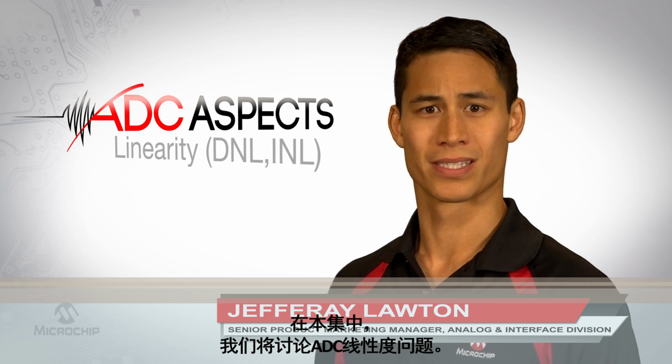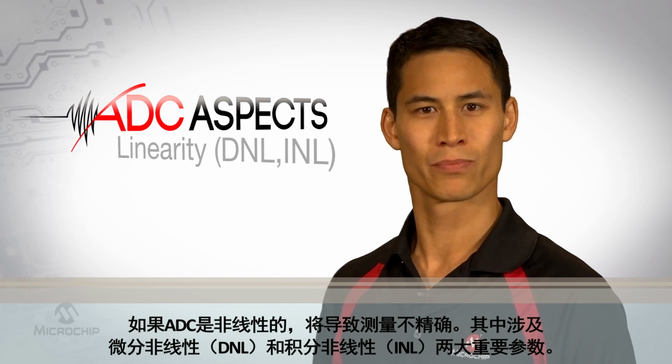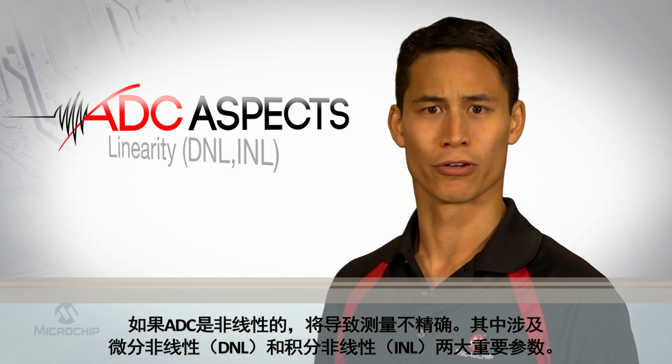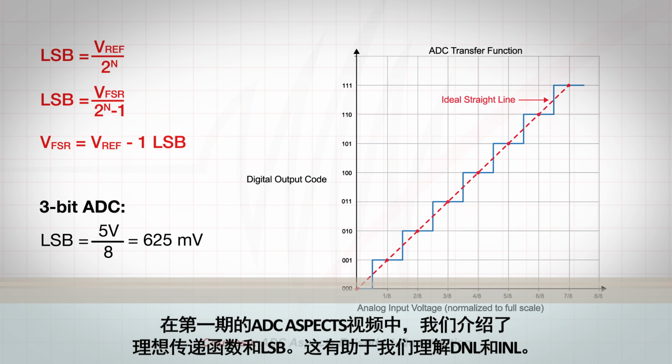In this episode, we'll discuss ADC linearity. When an ADC is nonlinear, it brings imprecision in measurements. Two important parameters are the differential and integral nonlinearity, or DNL and INL. In the first episode of ADC Aspects, we introduced the ideal transfer function and LSB. This will help us visualize DNL and INL.